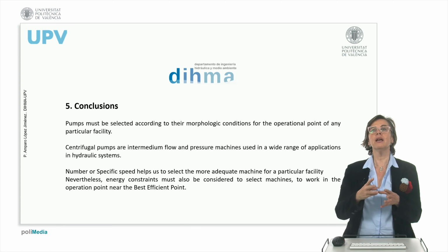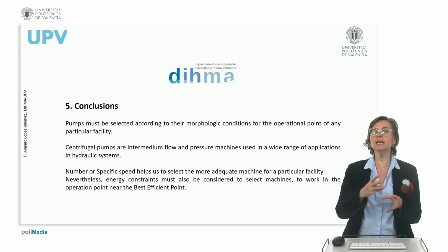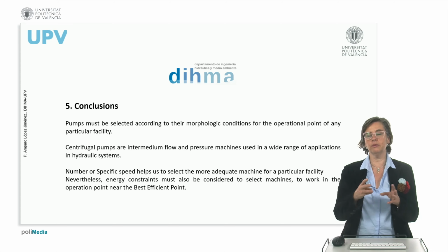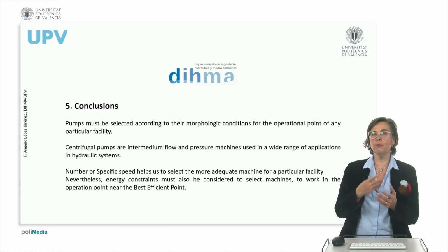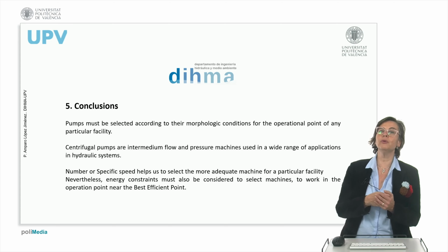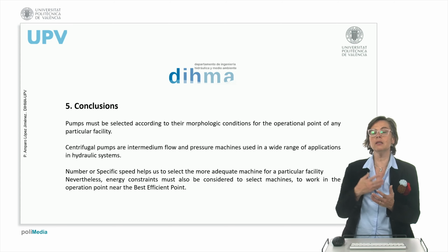They are medium head and medium flow machines, and they have a very small specific speed, which is very important. In order to select the machine, the curve and the operation at the best efficiency point must be considered, knowing the curve of the machine very well.